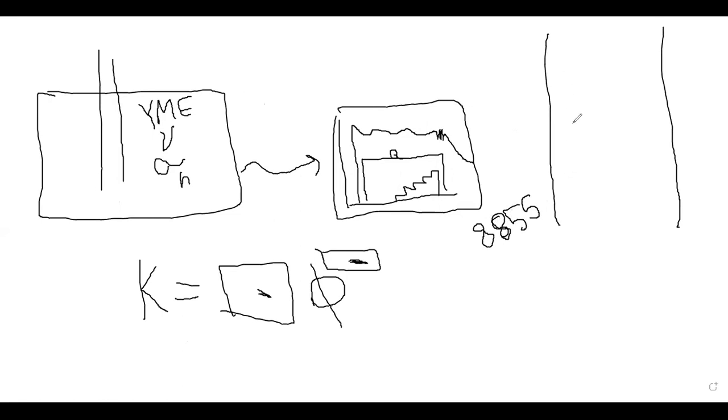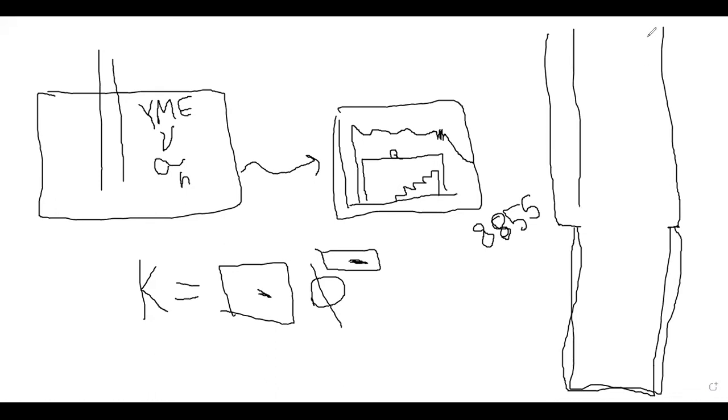Then we have a casing, a liner, till TVD. So the treatment tubing in our case will be 4.5 P110, then 3.5 P110 tubing. Then we set the packer at this depth.